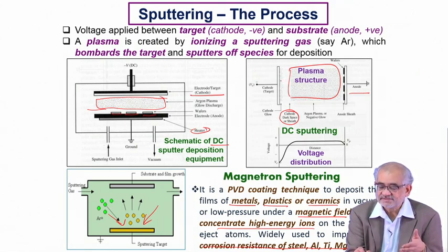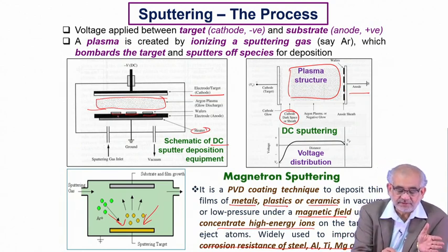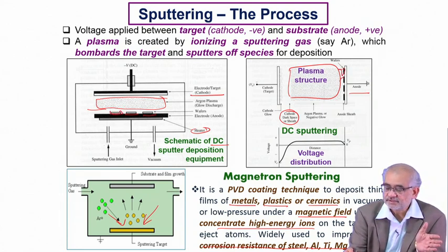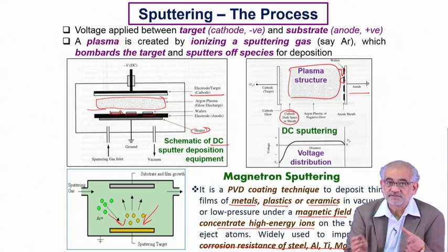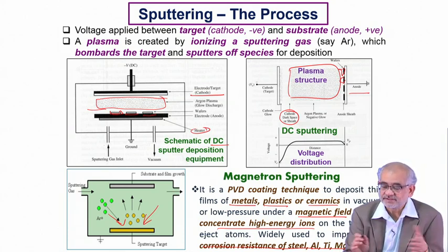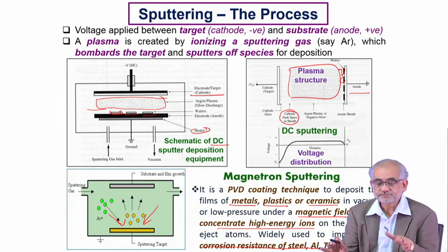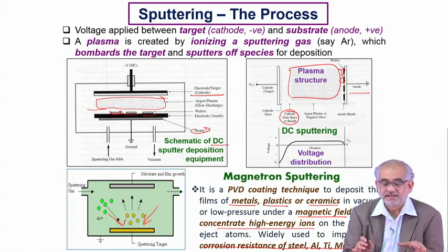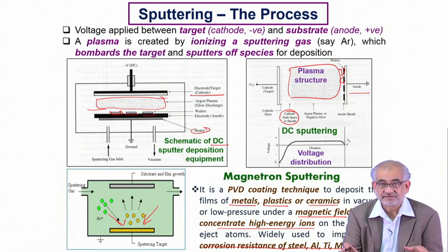The exact thickness, location and width of this region largely affects the overall coating thickness and the uniformity of the coating. One other thing that is very important is that if you look at this substrate here or this substrate here, they are tiny, much smaller compared to the overall dimension of the plasma that you create, and this is how you can make sure that there is uniform coverage and no shadowing effect, no non-uniformity.